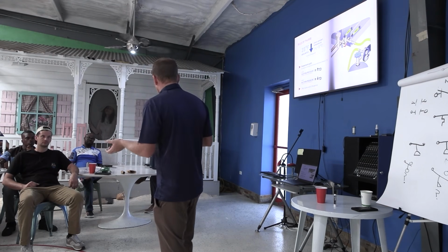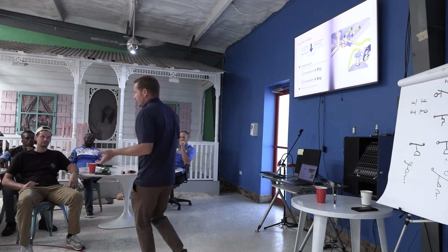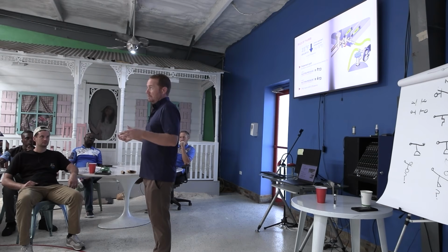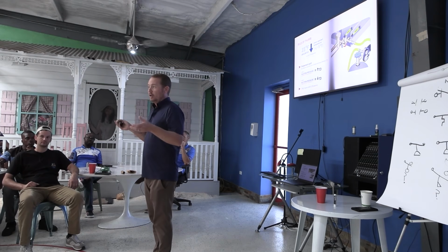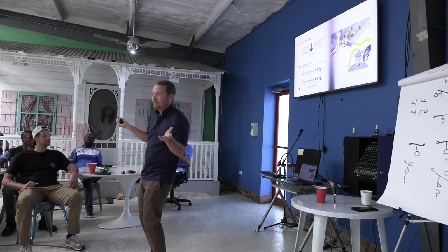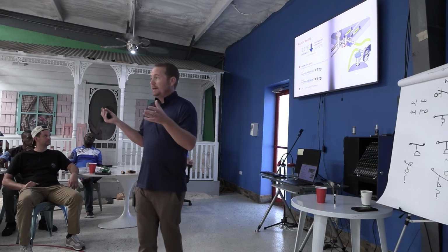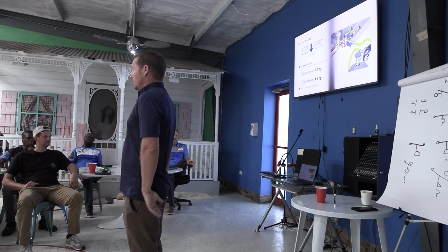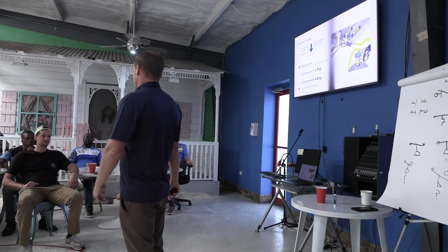That's what we call load. Load on the coil. Have you ever heard that before? What's the load on your evaporator coil? It's high load. That means the air is real hot, right? Low load. That means the air is real cold or you have poor airflow. That's all that means, right? High load means you're giving that evap a lot of heat to work with. Low load means you're not giving it very much heat to work with.